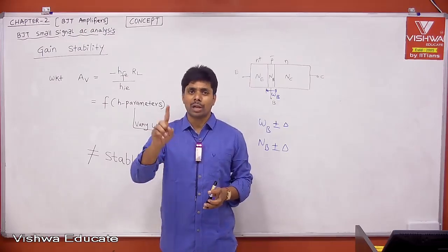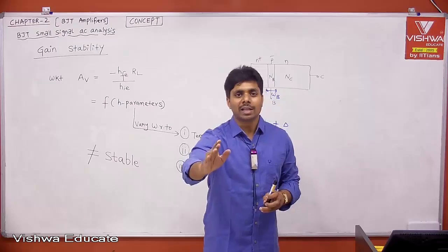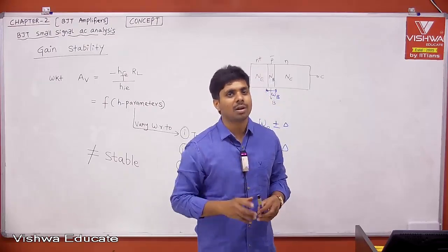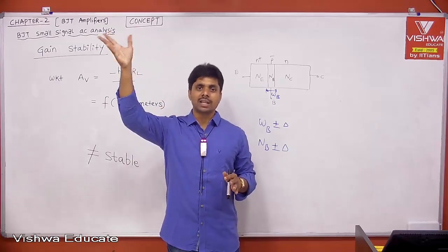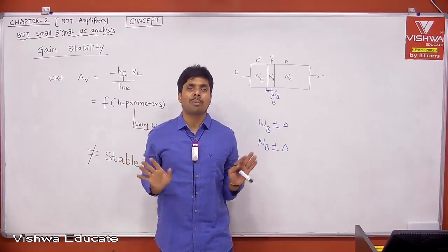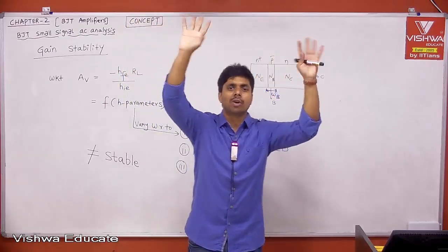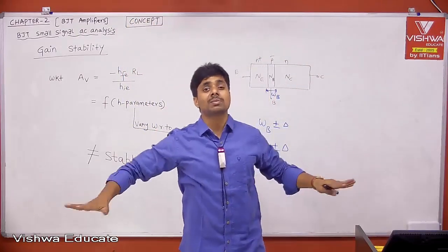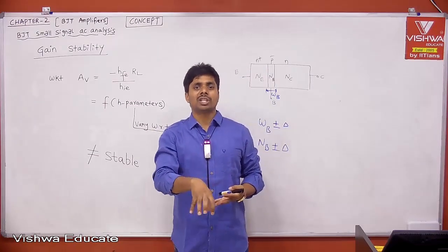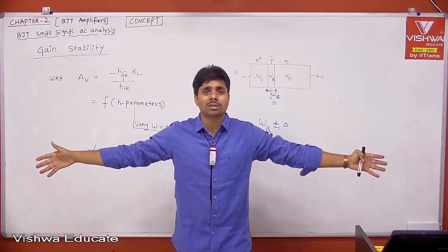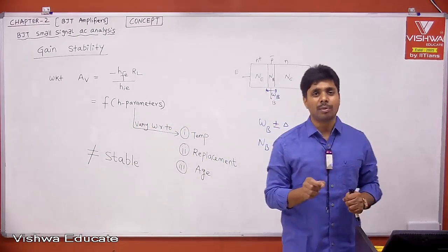But remember, the 2 lakh should not become 100 or 200. The open loop gain should not fall like that. No, that is not acceptable. Therefore, remember the gain variation that is acceptable in the case of op amp, because the gain itself is very high, and plus or minus something is not impacting your overall system's response. If the variation of a single sub-entity is not impacting the total system's response, it doesn't matter. Therefore, ultimately the requirement or the spec is very important.